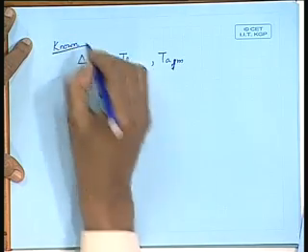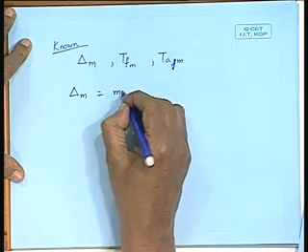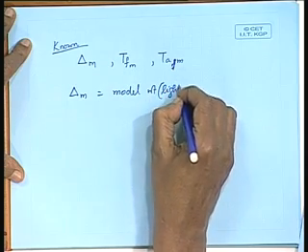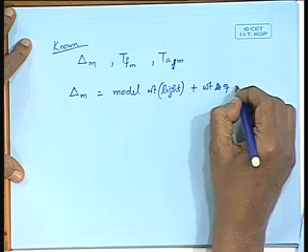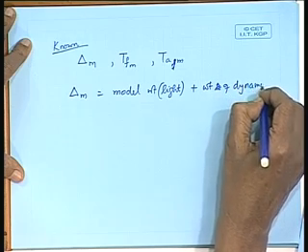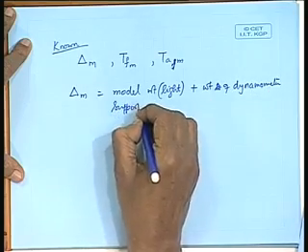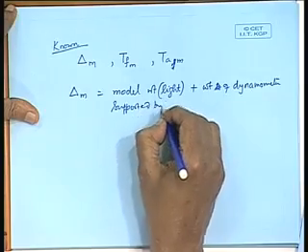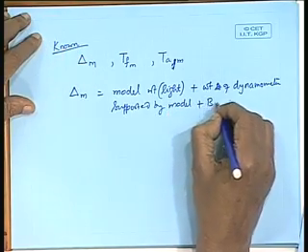So, the displacement of the model will be equal to the light model weight plus the weight of the dynamometer supported by the model. You see, this pillar will sit on the model, so that weight will come on the model and will not be held by the carriage. Plus, to get the proper displacement, we have to add ballast weight.